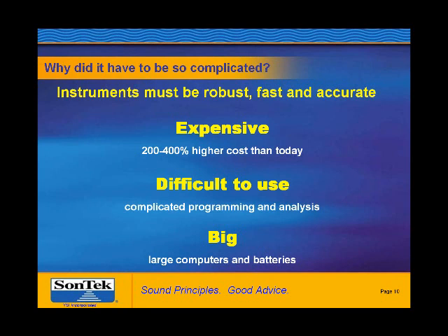And therefore, original wave instrumentations ended up being very expensive, difficult to use, and physically large in size. There are a few tips I just wanted to share, just from experience on deploying some of these instruments in the ocean. The most obvious one is make sure before you put something in the water that you're marking where it is that the system is deployed, as if you have to come back a few months later, you know how to find that system. A lost system does no good if you cannot get the data out of it, of course.